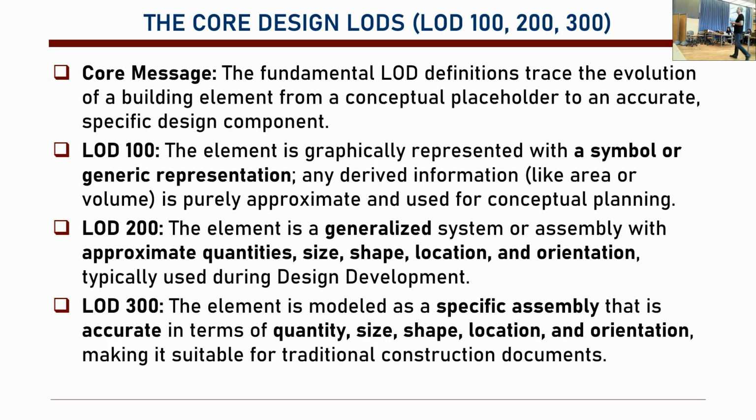That is the idea. Basically we have core design LODs: LOD 100, LOD 200, LOD 300. These fundamental LOD definitions follow the design evolution of the project, from a conceptual placeholder, a conceptual mass. Do we have any conceptual models here? Yeah, this is a conceptual model, right? If you ask what LOD this is, this is LOD 100. It is just a conceptual mass.